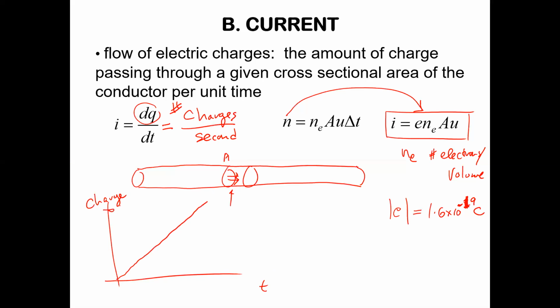Well, at a certain point, you can just say, let's figure out the rate of that line there, right? And that's dq over dt. You could do it over a small interval, where this becomes a dt, and this distance becomes a dq, or over a large interval, like delta q over delta t. If the current is constant, you're going to get the same rate. So basically, I is the slope of q of t. So that's a better conceptual understanding.